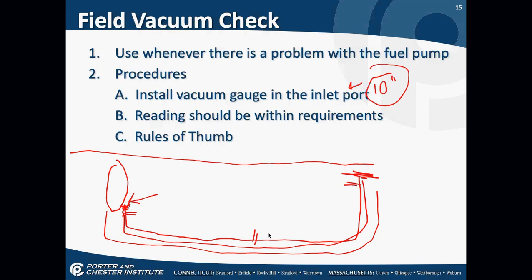That's why all new construction oil lines can no longer be buried under concrete floor. What happens when concrete and copper come in contact with each other? There's an electrical reaction that happens. It actually corrodes the copper away.